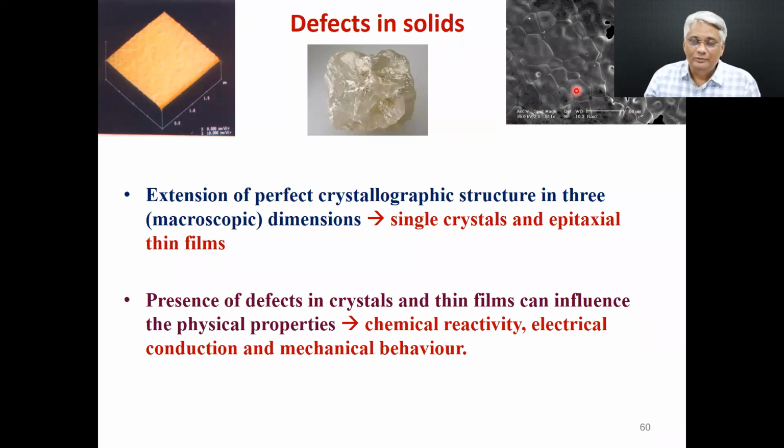I also mentioned, if you remember, if it takes 1 week to prepare a ceramic like a dielectric, like barium titanate, this ceramic can be used as a target material in one of the PVD processes, and you can convert this ceramic using a thin film growth process, a sputtering process, into an orderly crystalline thin film, which you call an epitaxial thin film, in time scales of a few tens of minutes.